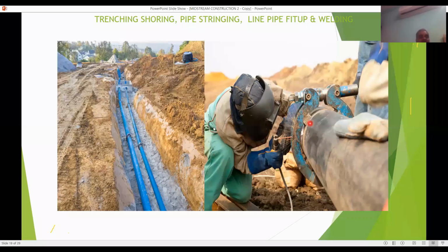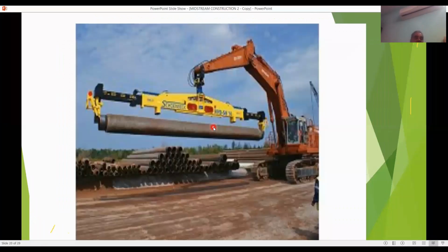You see the length, normally in the mechanical construction field, they say double random pipes and single random pipes. In cross-country pipelines, the pipes you see in the pipe-laying area are all double random pipes. Double random pipes means 12 meters length from this end to that end, plus or minus 10%. That means 11.7 meters to 12.3 meters. It is not exactly 12 meters. So if you lay and weld a 1 kilometer line, approximately 83 joints will come in 1 kilometer.